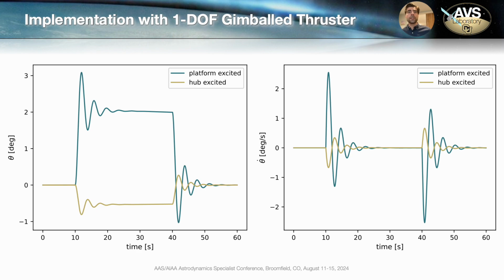And not only do we get this more realistic flexing in the opposite direction, but also a larger magnitude, as the same force applied to the smaller mass and inertia of a robotic arm creates a larger deflection than otherwise accelerating a likely more massive hub.